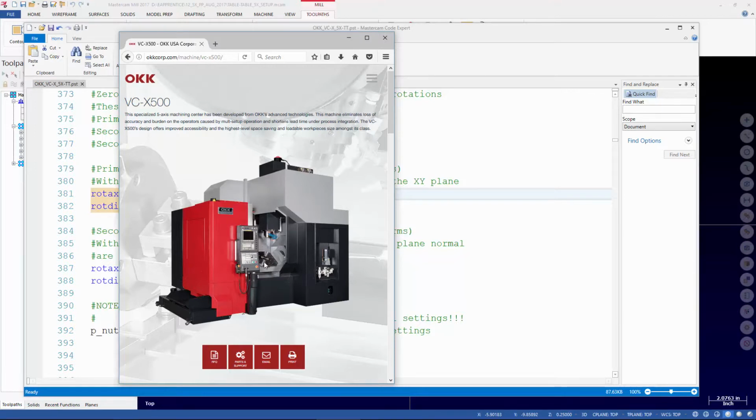So if we're on a table, we just want to be able to tilt the table, right? We want to be able to tilt A to -90 and have this platter be vertical instead of horizontal. We want it to be measurably up and down and facing towards the operator in a vertical configuration. And in order to do that, the 0 point on that is critical.